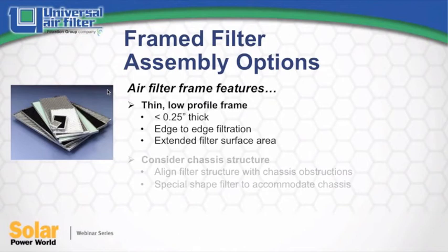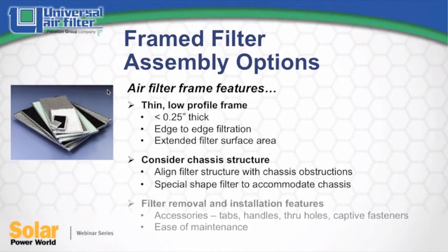Precision sheet metal fabrication and custom manufacturing capabilities allow equipment designers to utilize all space available to maximize cooling airflow. Rule number 1 is do not design your chassis around a standard air filter available on the shelf. Design a custom air filter to meet the specific equipment protection needs of your project.